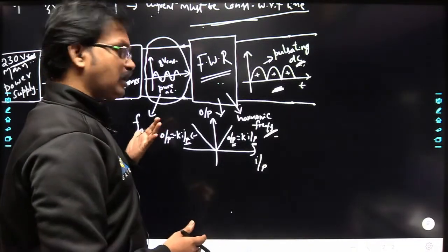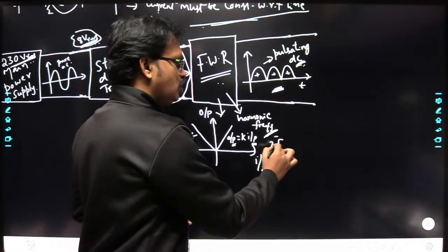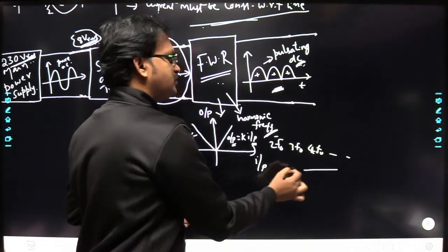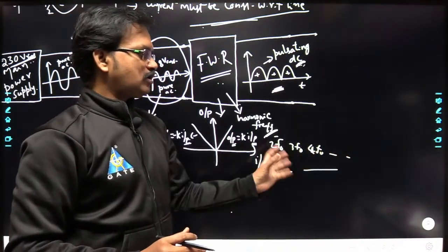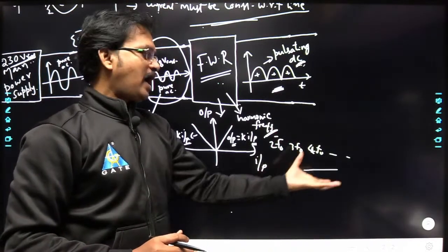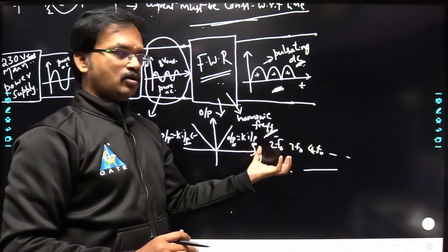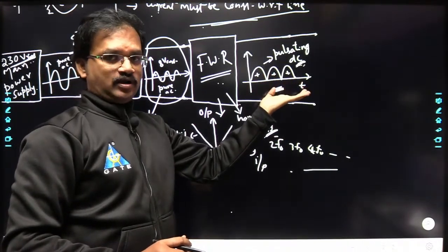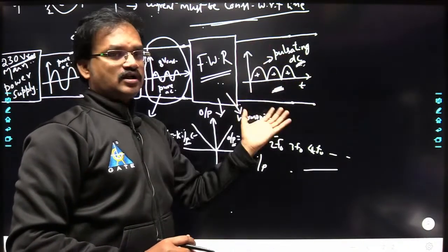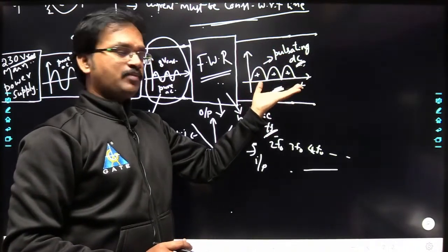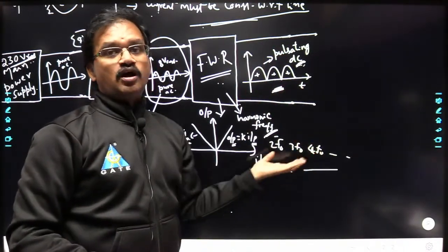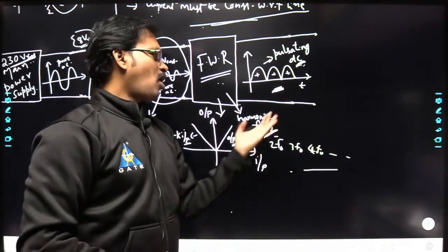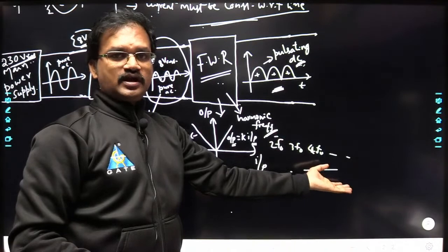That means here, if you have f0, it is going to generate 2f0, 3f0, 4f0, 5f0 and so on. All these are nothing but higher frequency components. So adding all these components together, you are going to get finally a distorted output waveform in this manner. So this signal is made up of these harmonic frequency components, yes or no? Now here you have all the higher frequency components.